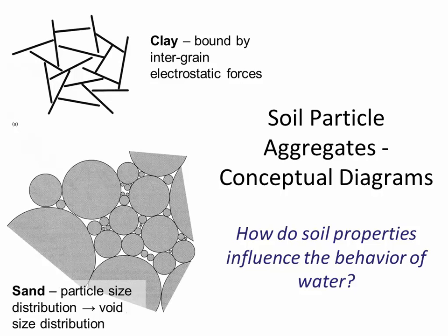And since they have a high surface area, and because of their small size, the clay particles actually have a charge to them. They have a negative charge. These small, thin layers of clay basically have a negative charge all around them, and the water is attracted to that negative charge. And their high surface area also means that, maybe the crude way to think about it, it's hard for water to make its way through these voids because they're so small. And because there's so much surface area, the water is trying to seep around a very high area before it makes its way through a thick column of soil.